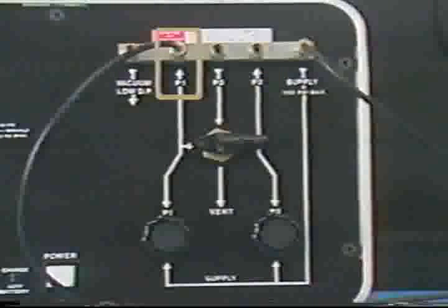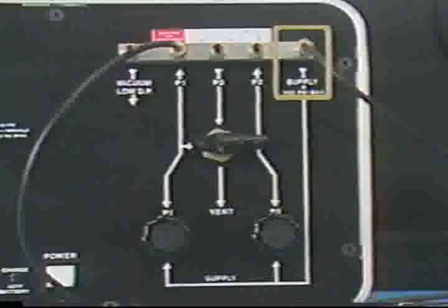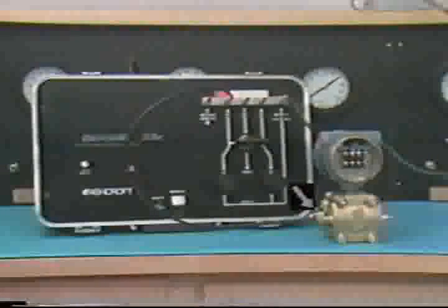This connection point is used to connect the transmitter to the pressure calibrator. According to the manufacturer's instructions for this calibrator, the transmitter should be connected to the P1 output port on the pressure calibrator. The pressure calibrator also needs 30 psi supply air in order to produce an output. The output from the pressure calibrator is connected to the high-pressure port on the transmitter to provide input pressure. The low-pressure port should be vented to atmosphere. This provides a reference point for the differential pressure measurement.